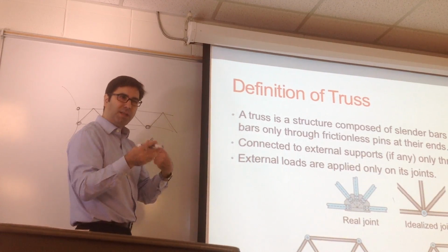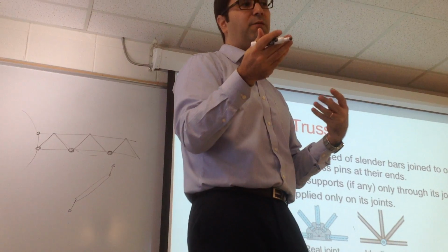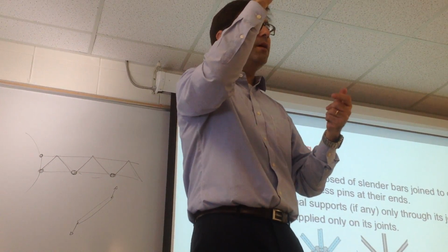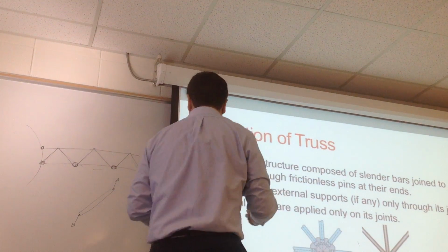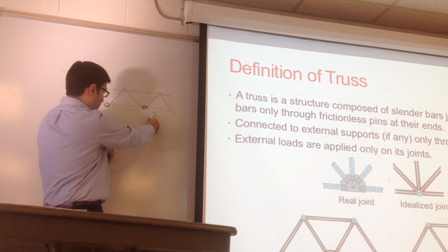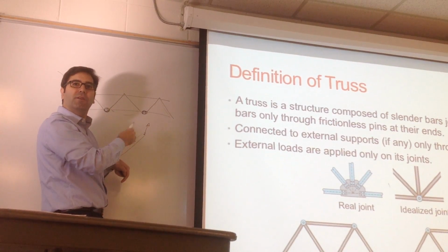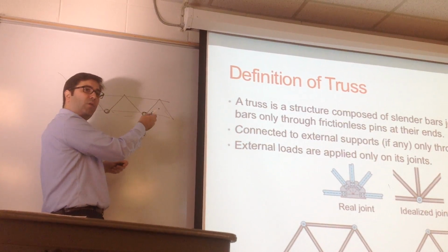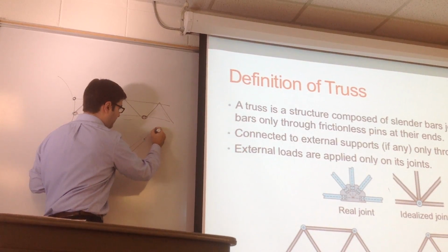Right? But then there is another equation of equilibrium. I don't know if you saw it, but I can tell you intuitively, sum of moments equal to zero, which means you don't want this structure to rotate, okay? So if we have a bar like this and we apply forces like this, what's going to happen? It's going to rotate clockwise or counterclockwise in this case? Counterclockwise, right? So you get that intuition. So the only way for this not to rotate is that these forces are equal and opposite, but also along the line of the direction of the bar.